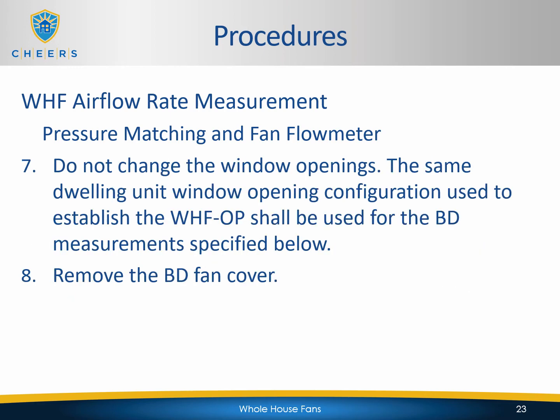Okay, once you have the windows set for that 10 pascal difference, you don't want to change them at all. So leave them exactly the same. The same window opening configuration is going to be used to establish the whole house fan operating pressure for the blower door measurements that we're going to talk about next.